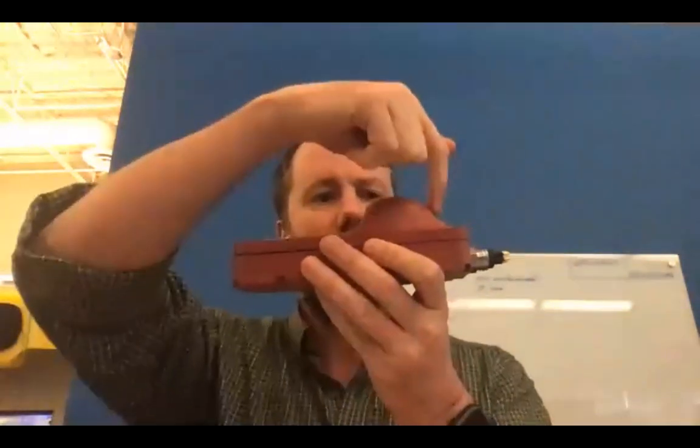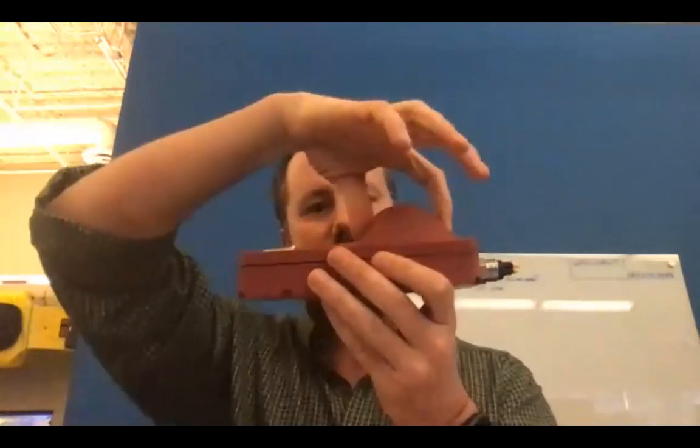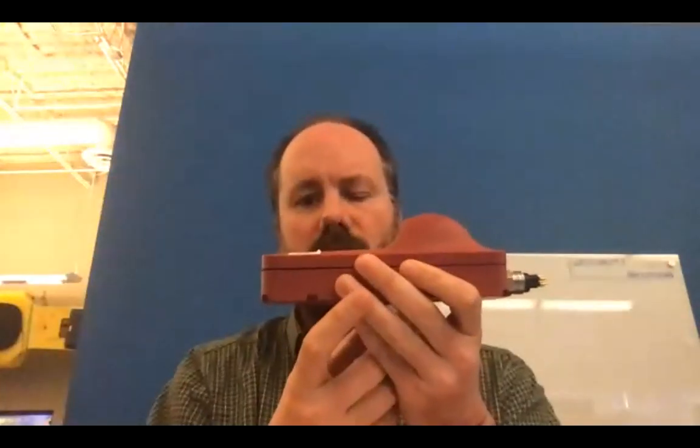The same occurs on a glider, that the induced electric current that's in the water circulates around horizontally and vertically over this cell. It doesn't circulate below. So it doesn't really matter what you have in the wet bay underneath this instrument. You could have battery packs, all those kinds of things, and it makes no difference at all. It's really things that must be in the water and they must be in the area of field concentration to be detected.